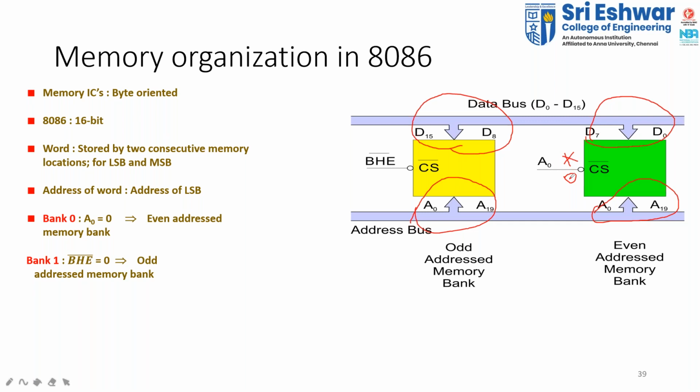So you have to give 0 to this particular chip select signal. It is mandated, just like how we give supply and ground to individual ICs. It is mandated to give the chip select signal to make your IC get into the active state.